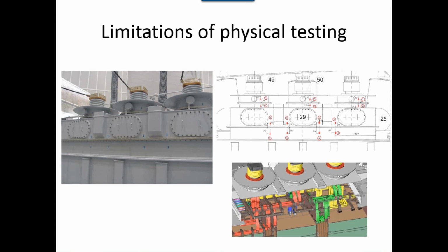And obviously for people who design electrical machines, where induced current is of concern, one would like to reduce the eddy current losses, and for designers and users of transformers and those type of devices, core losses also need to be reduced. And finally, one needs to identify the hotspots in one's design, and also we would like to try and eliminate some of these hotspots from critical components.